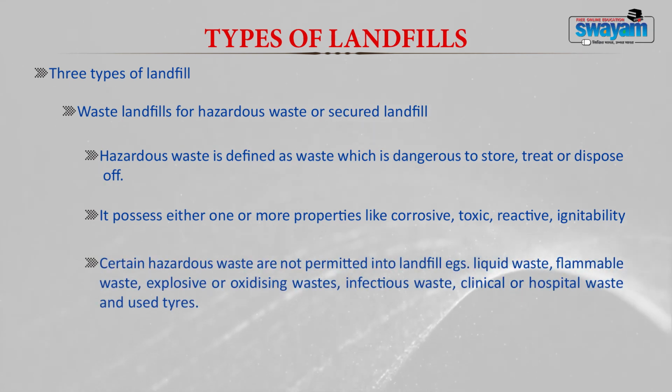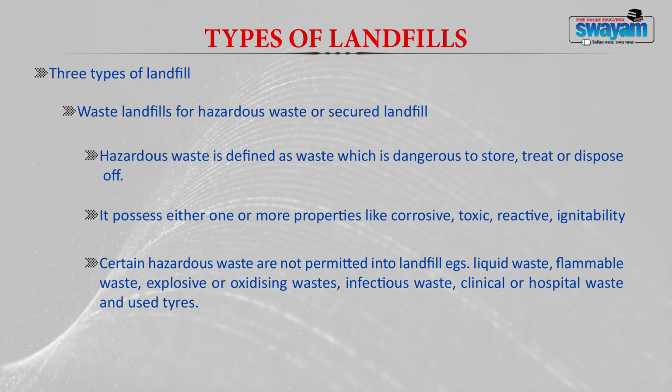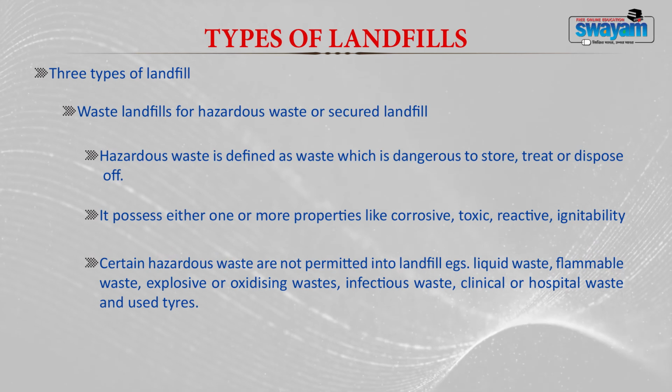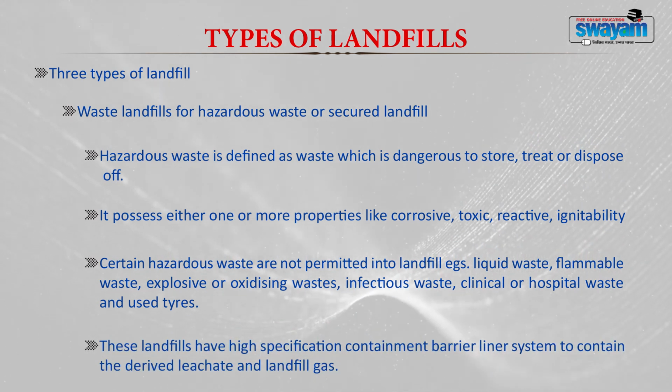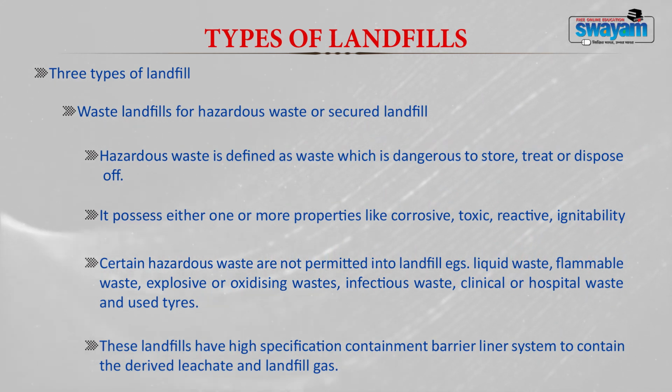Certain hazardous wastes are not generally permitted into landfills. Some of the examples can be liquid waste, flammable waste, explosives, oxidizing waste, infectious waste, clinical or hospital waste, and used tires, which are not allowed in a secure landfill. Now, these landfills have very high specification contaminant barrier liner systems, so as to avoid leachate entry and landfill gas emission, because a small contamination will lead to a very big health and environmental hazard.